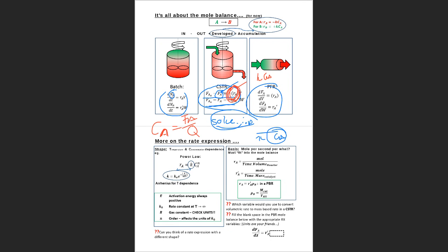So for each step, as you are integrating over a PFR reactor, this is part of your algebra when you are solving your rate equations. You integrate over molar flow rate, and you solve for molar flow rate in a CSTR. And in your solver function, you will have a sub-calculation where you calculate concentration and where you calculate your rates.